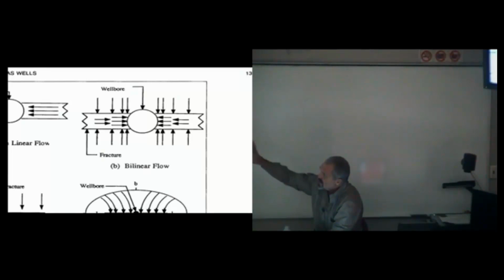So bilinear flow, from an enhanced oil recovery mindset, is I'm gas flooding a water frac. And so where do I flood that first? I flood it, see where the three arrows next to the wellbore area are? I'm flooding it first there because my reservoir sees the well as the largest, lowest point in pressure.